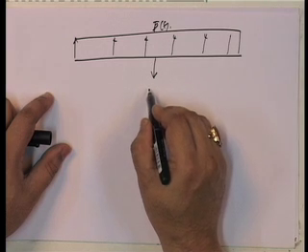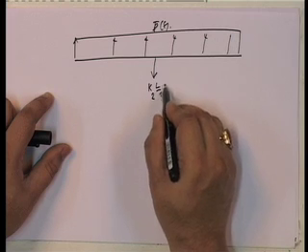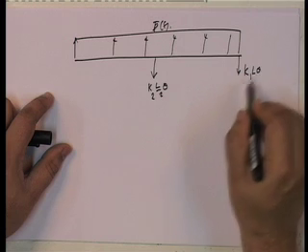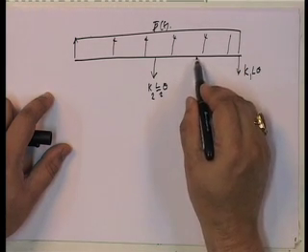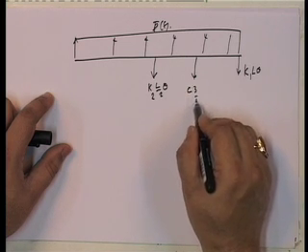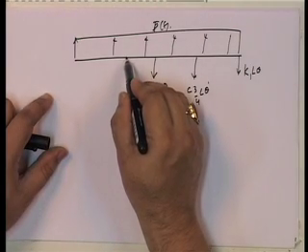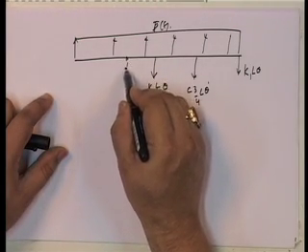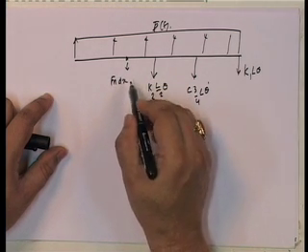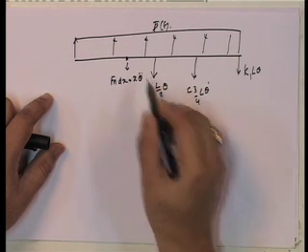Then we have the force here, which is equal to K2 into L by 2 theta. Then we have K1 into L theta. Then we have C into 3 by 4 L theta dot, and we have m bar dx into x theta double dot.